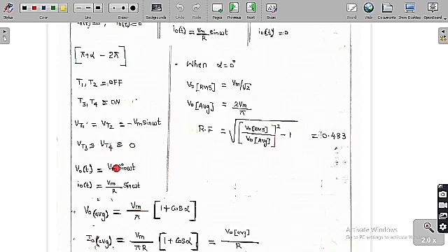So V naught of t is equal to the negative of the source voltage, or simply V naught of t is equal to minus Vs of t. So finally we are going to get V naught of t is equal to Vm sin omega t and I naught of t is equal to Vm by R sin omega t. So you are going to get these graphs.